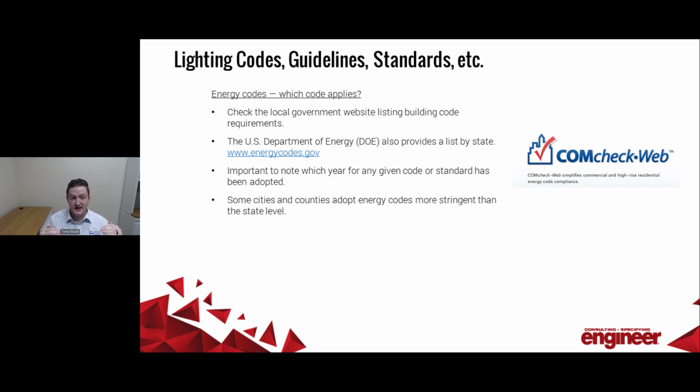And you really needed to understand both of those things at the same time, because you might have been in a position where, say I'm in Omaha, a renovation project might not have needed to apply the state code. In many cases, they didn't, but there was still a locally enforced code. So that's a cautionary tale to make sure that you are looking at both the state and local codes to see which ones are going to apply, because the state code might not matter at all, but you might still have a code requirement. So make sure that you're checking all of those layers of different code requirements and that you're meeting the most stringent code that you're required to meet.